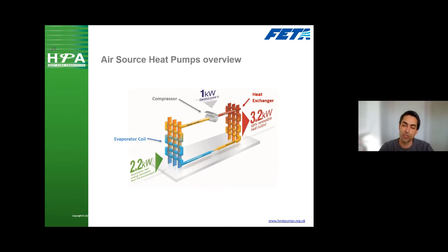It's this evaporator coil that we effectively manipulate to change the type of technology. And for this case, under an air source unit, it's a finned evaporator coil that we run our ambient air across to draw all of that nice latent energy and sensible energy that sits within the air and use it to warm up our refrigerant to run it into this cycle.